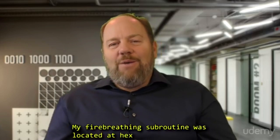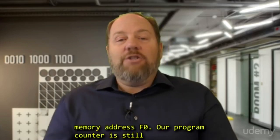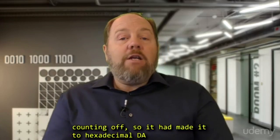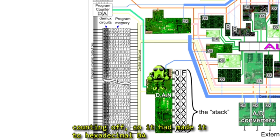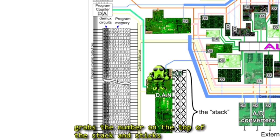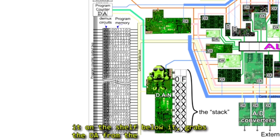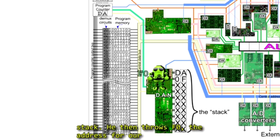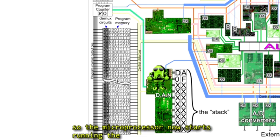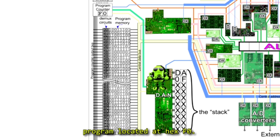My fire-breathing subroutine was located at hex memory address F0. Our program counter is still counting off, so it had made it to hexadecimal DA when I hit the big orange button. So Dan the Man grabs the number on the top of the stack, sticks it on the shelf below it, grabs the DA from the program counter, and puts it on the top of the stack. He then throws F0, the address for our orange button subroutine, into the program counter, so the microprocessor now starts running the program located at hex F0.